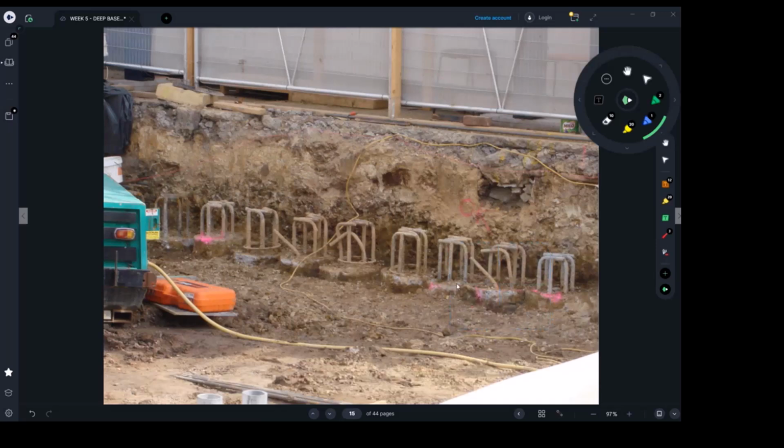So what they do, because they can't do this maybe in the same day, they're gonna do the blue ones. They're gonna hit one and miss two, and hit this and hit that. They're gonna use the hit and miss method. So day one, they're gonna do every third pile, or every fourth pile. Again, there's gonna be a meeting between the construction engineer, the soil engineer, and the structural engineer, and they're gonna discuss this. They're gonna tell him you have to do every third pile or fourth pile or second pile.